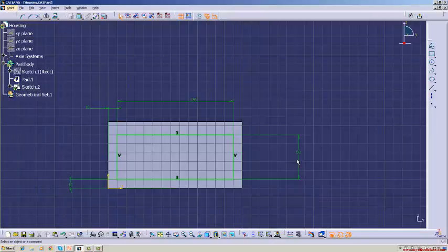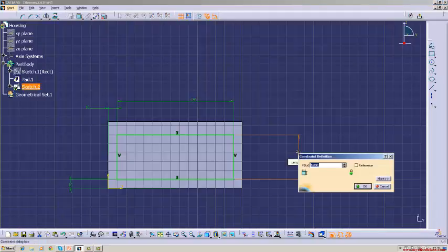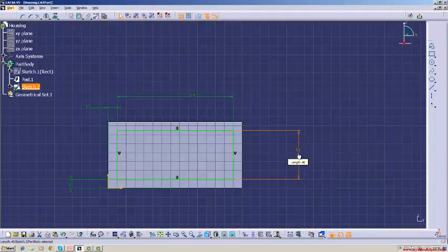And this is 50. This is 10. You want to make that also 10. This has to be 55. Okay. Or you can remove this and assign from here to here a dimension, a constraint. 10 it becomes 20. You cannot assign both.